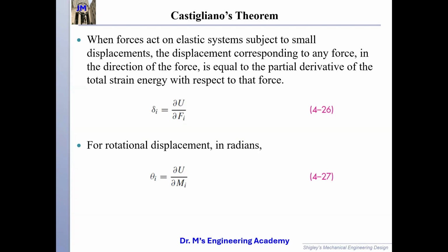All right? So you need to know that is delta i and Fi, and you must be talking about the same point in the same direction. Can you write down, guys? Same point, same direction. And because the force usually has three directions, F1, F2, F3, correspondingly you should have delta 1, delta 2, delta 3. That means the displacement in three different directions. All right? Be very careful. So this is one case.